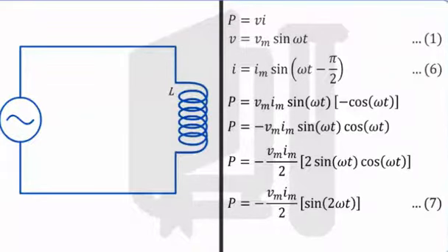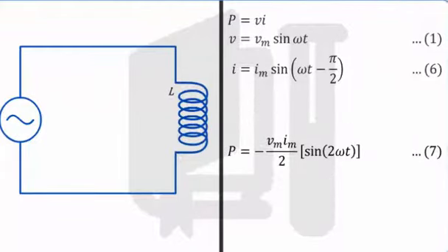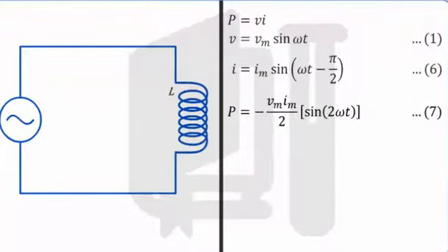This instantaneous power evaluates as a time-dependent harmonic function. As this is a time-dependent sinusoidal function, its average over one complete time period will be 0. The argument of sine function for voltage is omega t, and for power is twice omega t.